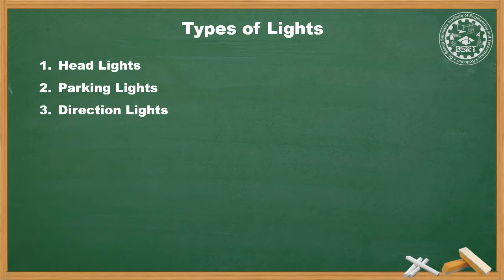These include the blinker lights. These give a red signal light to indicate when high beams of headlamps are burning, to indicate when the parking brake is applied, to indicate that oil pressure is low, cooling water temperature is too high or too low, or the generator is not charging the battery. These are the blinker lights presented on the dashboard of a vehicle.